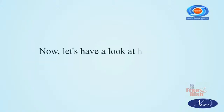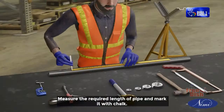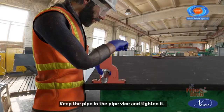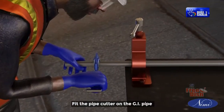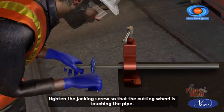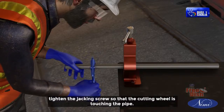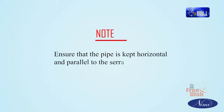Now, let's have a look at handling of pipe flaring and cutting tools. Measure the required length of pipe and mark it with chalk. Keep the pipe in the pipe vise and tighten it. Fit the pipe cutter on the GI pipe on the scribed line and tighten the jacking screw so that the cutting wheel is touching the pipe. Note: ensure that the pipe is kept horizontal and parallel to the serrations such that the marking is visible at the top.